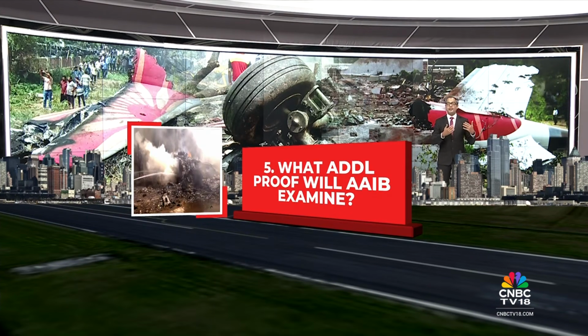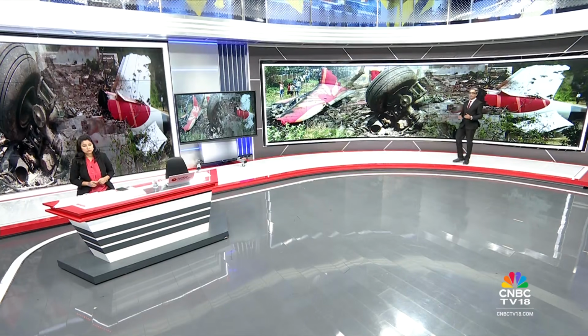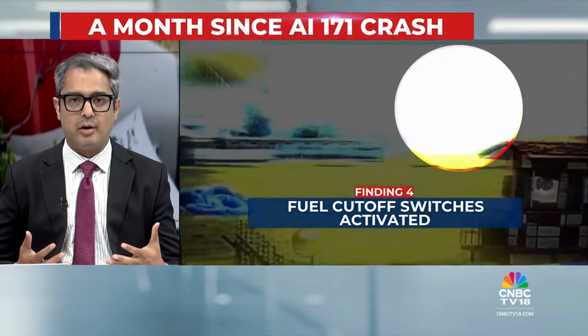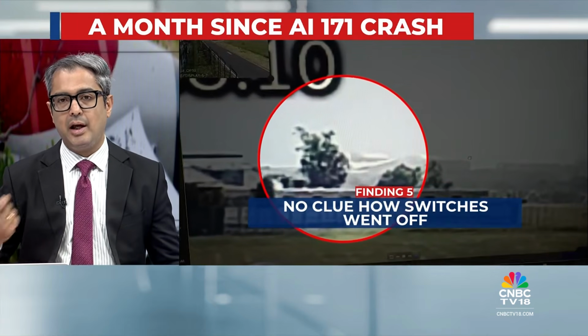Number 5, what additional proof will the Aircraft Accident Investigation Board examine to try and come to the exact conclusion as to why Air India Flight 171 crashed? For now, what the report says is that the fuel cutoff switch, which had to be in run position, was in cutoff position, and the pilot and the co-pilot realized this by the 4th or 5th second after takeoff, and then right after that they moved it back into the run position. By the time they moved it back, there wasn't enough elevation, there wasn't enough altitude, there wasn't enough power for both the engines to be relit and for the flight to continue.